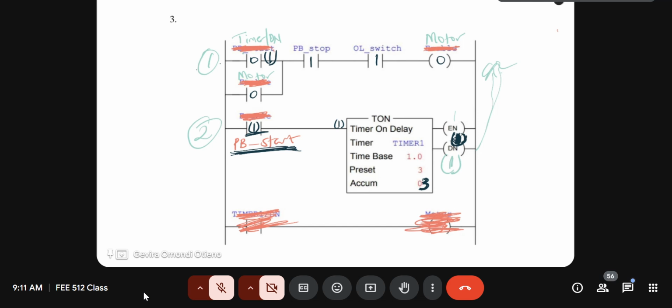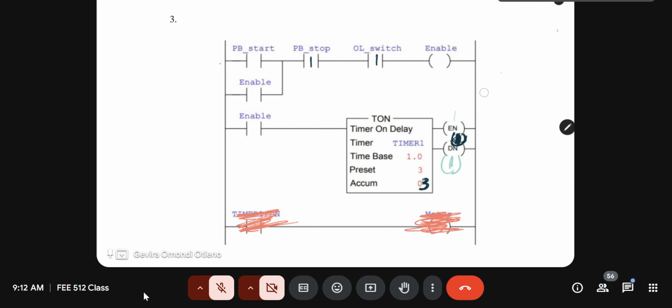Yeah, mine was just about dealing with the timers as well, where maybe you have the timer controlling a counter. I realized that when you just connect the timer directly with the counter, you will obviously need that pulsating signal to reset and set the timer as well to maintain that counting. Because we've already completed this, that's just what I wanted to ask you. Maybe I can present a simulation, just for a better understanding of what I'm saying.